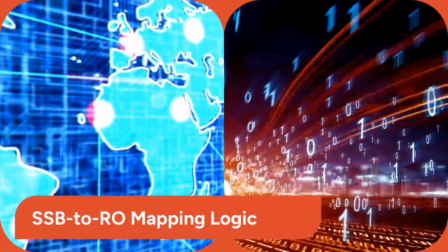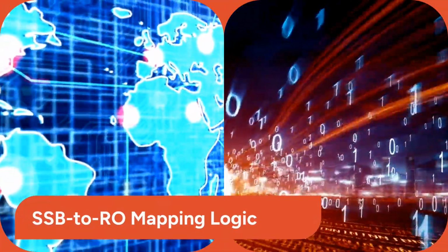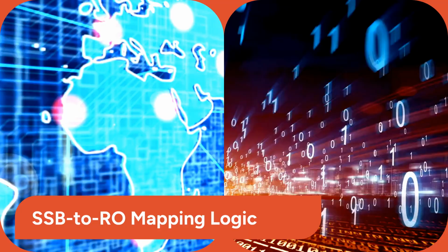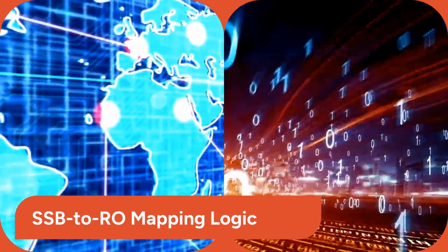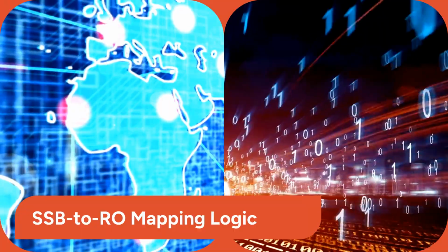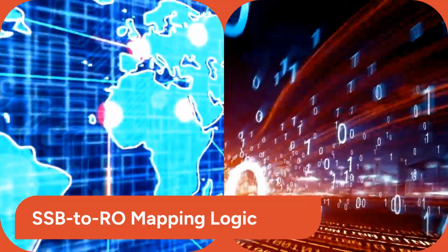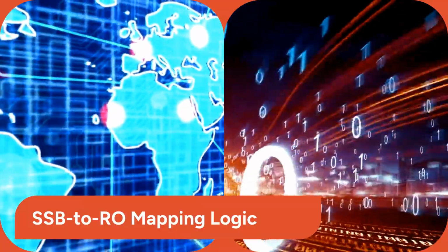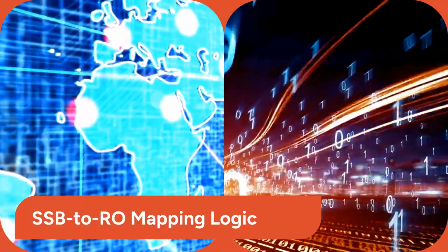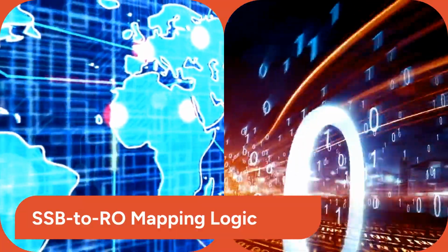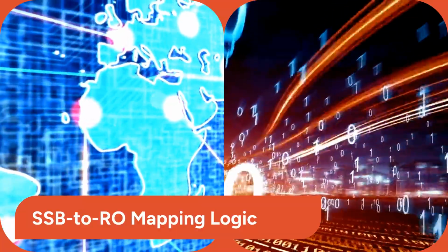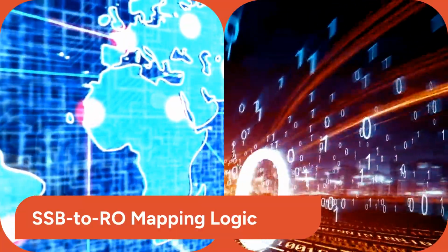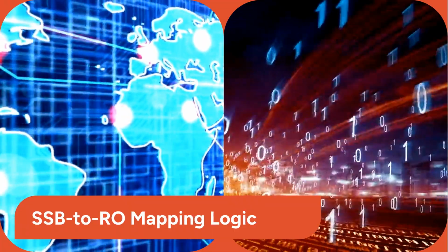The gNodeB schedules physical time-frequency resources called PRACH occasions, or ROs. The mapping between SSBs and ROs can be configured dynamically. A one-to-one map provides high spatial granularity but increases overhead. N-to-one mapping means multiple SSBs share the same RO, which conserves resources but reintroduces contention. Conversely, one-to-N mapping allocates multiple ROs per SSB, beneficial in high-traffic scenarios. This mapping is vital for the gNodeB to immediately know where to steer its uplink receiver array.